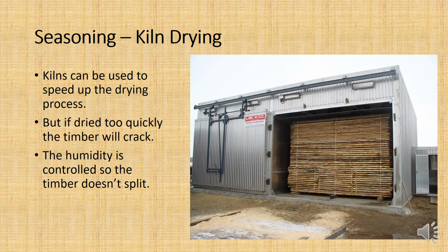Instead, they will split apart, and you will end up with big splits in the wood, and that loses all of the strength in the timber. The other thing you need to remember with kiln drying is you've got to have extractor fans to get the humidity out of the timber, because if you have a big closed shed like that and you're heating the wood inside,